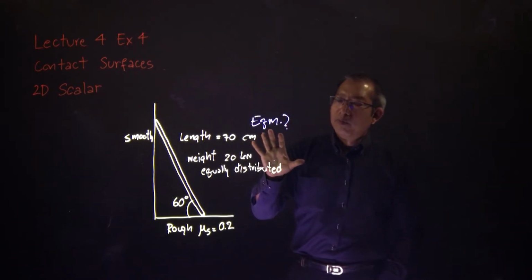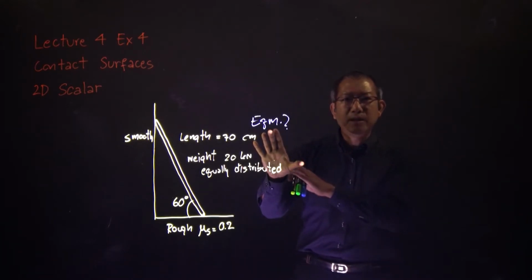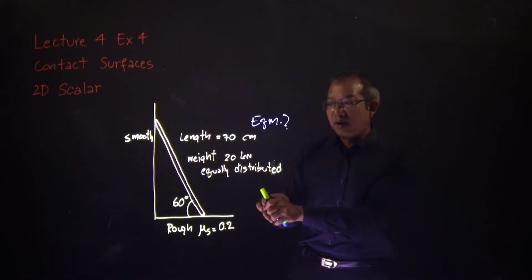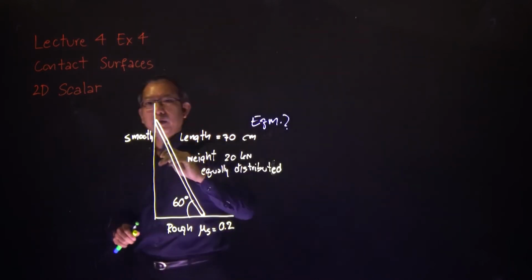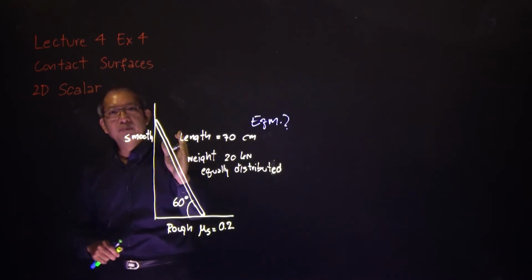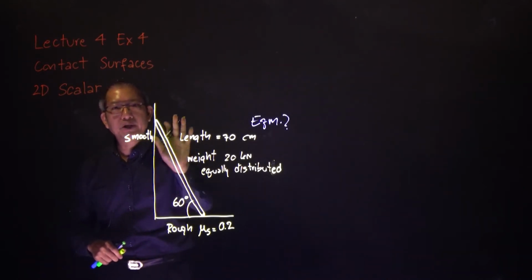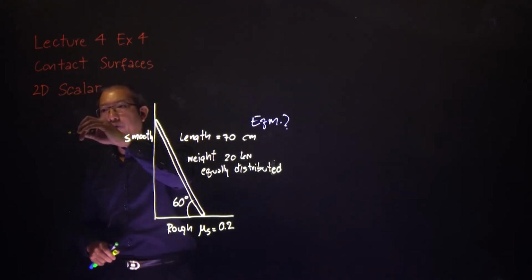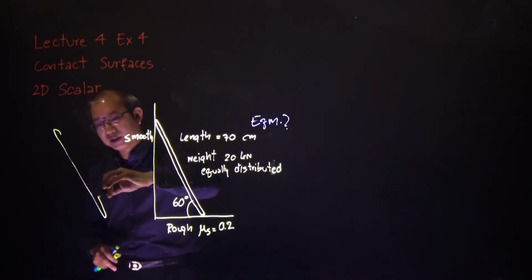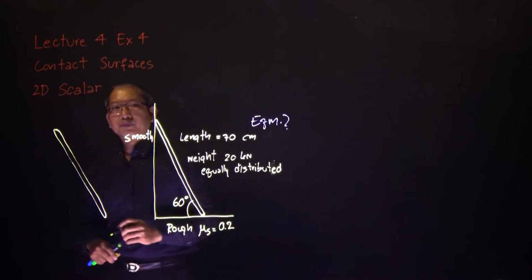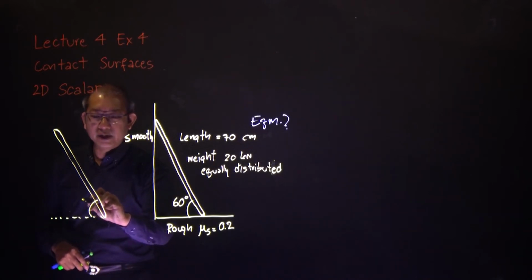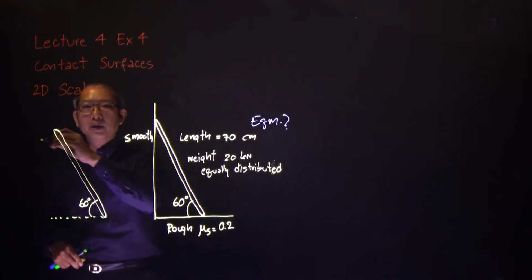So let's see. When we talk about calculating forces and moment, the next thing we think about is the free body diagram. So let's do the free body diagram then. Now, the stick itself, this is not the free body diagram. To draw the free body diagram, it has to be removed out of the environment, so it cannot be drawn on this. Therefore, draw it apart. Then we start off with the body. In this case, we talk about a stick. Now, if this one here to the horizon, the floor, is 60 degrees, correct? According to the question.